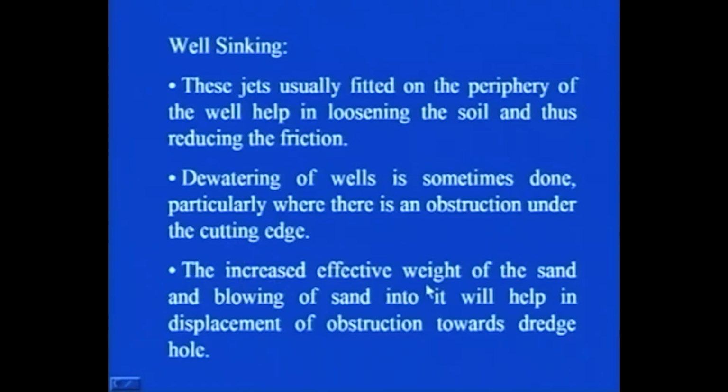The increased effective weight of the sand and blowing of sand into it will help in displacement of obstruction towards the dredge hole. So in case the dewatering of the well is done, the effective weight of the sand gets increased and the blowing of sand into it helps in the displacement of obstruction near the dredge hole.